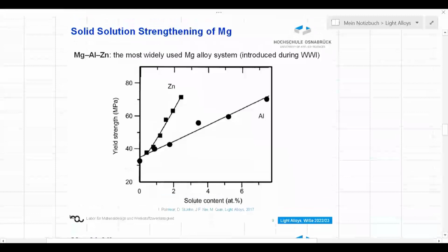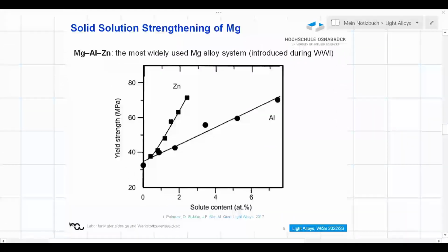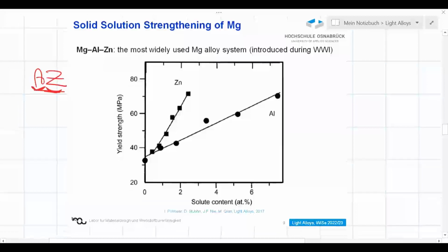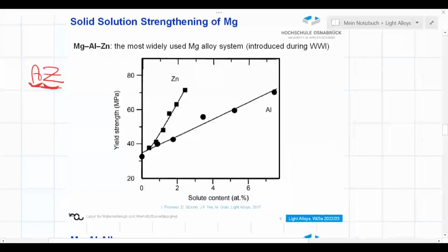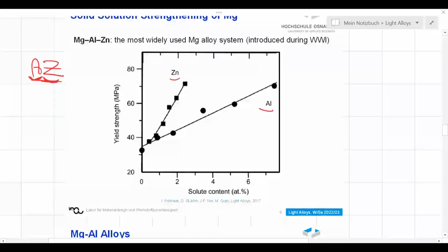Good. Right, as I mentioned, these AZ types of alloys are very important ones, the ones which contain aluminum and zinc. Let us see the function of these alloying elements. What happens if aluminum and zinc are there? By addition of aluminum, we could expect solid solution hardening. This is something which we expect from alloys. We are mixing two metals, and by that, we are going to get a change in the strength values. And here, aluminum is effective. It makes these alloys stronger.